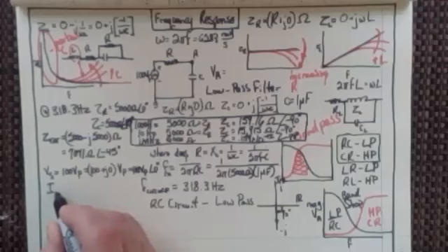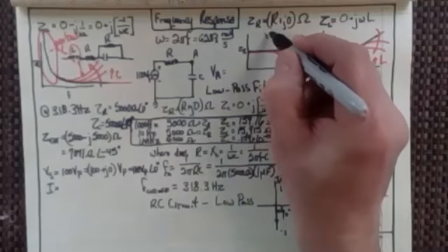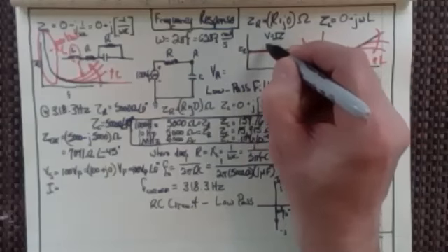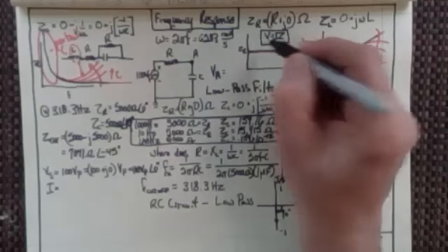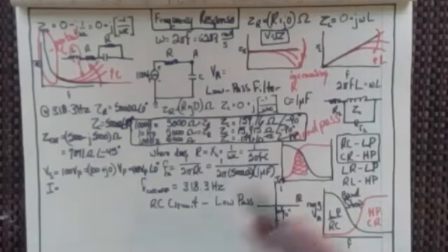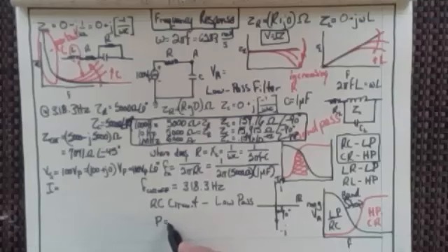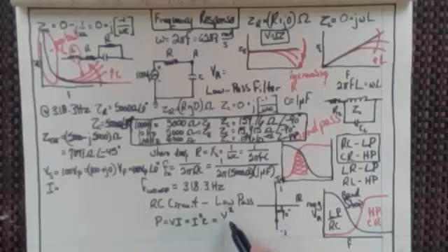What is my peak current? Because I know Ohm's law. I love to write Ohm's law, by the way. V equals IZ. And let's put a box around it. Don't ever forget that. Oh, and you also want me to write the power equations? Yes, that's right. Power equals VI, right? Or it equals I squared Z, or it equals V squared over Z. And remember, all of these are RMS for power, right? All RMS for power. So let's get back here.